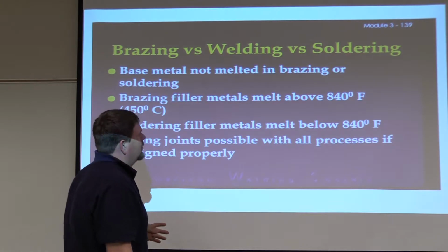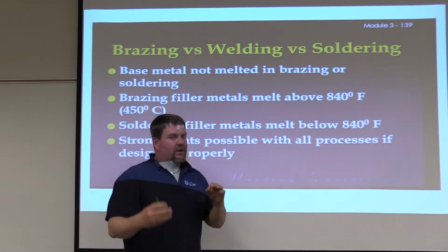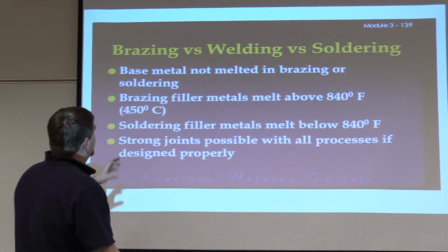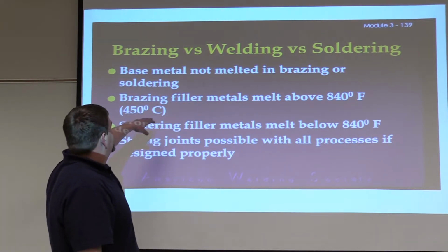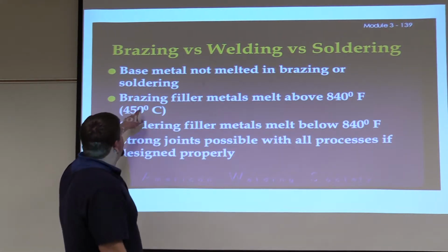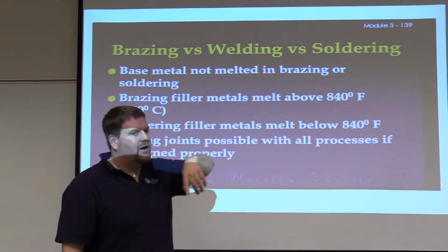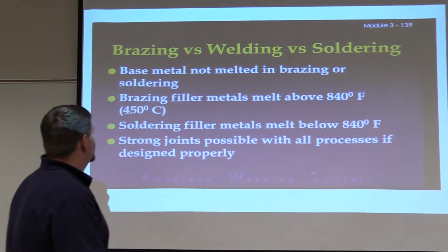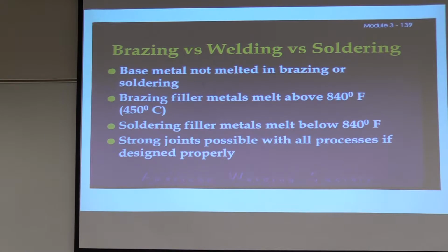2,780 generally, okay? Depending on carbon content and chemical makeup, but that's what we consider 2,780, 2,800. So brazing's below that, welding is above that naturally, okay? Brazing filler metals melt above 840 degrees. Soldering is anything below 840 degrees, okay? Remember that number, 840 is an important number.